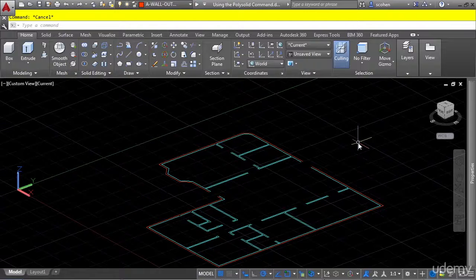You create multiple segmented solids using the Polysolid command. Multiple segmented solids are 3D solids that consist of a rectangular profile and a single line path the rectangular profile follows. When creating a solid using Polysolid, you first set the width and height values for the rectangular profile. Then you draw the path of lines and arcs like drawing a polyline, or you can select existing geometry to define that path. Being able to set the size and create the path of the solid is vital to achieving the proper final results.